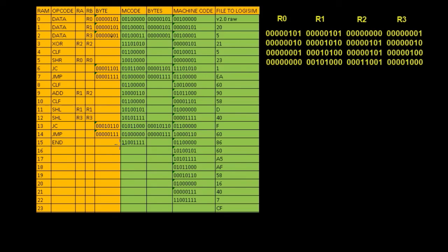Now it's a bit of a mouthful and it's a bit dull listening to that. The best way to do it is for you to work through it yourself. If you set up the registers, so we say register R0, R1, R2 and R3, you put in the initial values and then you work through the values on the register as you work through each of the cycles, each of the loops, and you'll see the registers changing, and eventually you'll see the final answer will be in register R2, which will be this 11001, which is 5 times 5, which is 25.